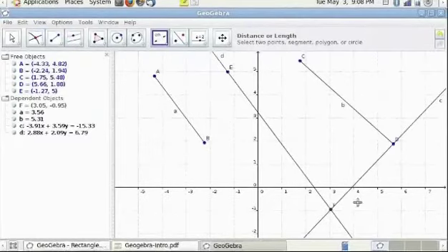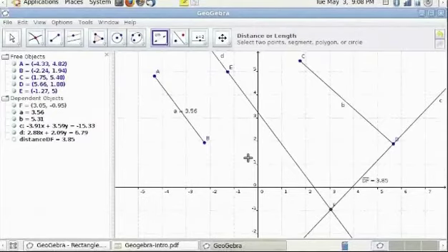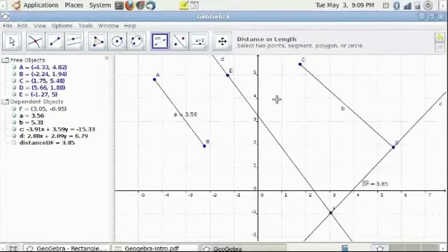To measure the distance, click on the fourth tool from the right on the toolbar and select the Distance or Length tool. You may measure the distance between points by selecting the two points, clicking D and F here, or you may select an entire line segment. Notice that there are no units on the grid. We will explore unit names in more advanced topics.